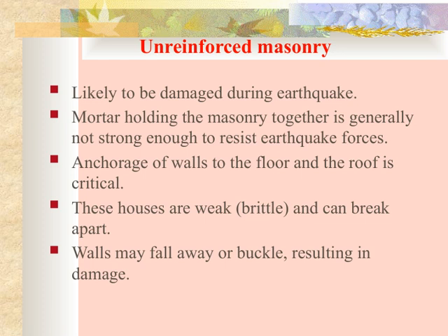Another critical point is the importance of anchorage, how well the walls are connected to the floors and the roof. If these connections are weak, the entire structure becomes unstable. Think of it this way: if the walls aren't securely attached, they can break apart or buckle under stress. These types of houses tend to be brittle and can break apart quite easily. During seismic activity, you might see walls fall away or buckle, leading to significant damage. This highlights the overall importance of retrofitting and strengthening masonry structures to improve their resilience against earthquakes.